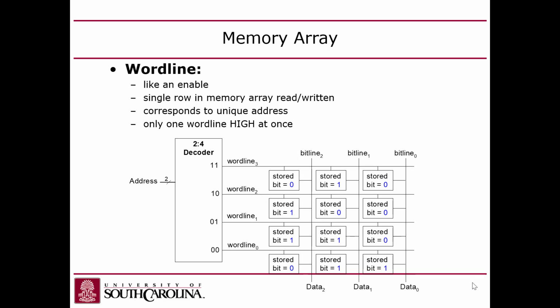So that's why the level 1 cache, which is a small RAM, is faster than level 2 cache, which is faster than level 3 cache, which is faster than level 4 cache, which is faster than the off-chip RAM. That decoder is the reason why larger memories are slower, because larger decoders are slower; the logical critical path in there is larger. So this is the whole explanation as to why we have a memory hierarchy.